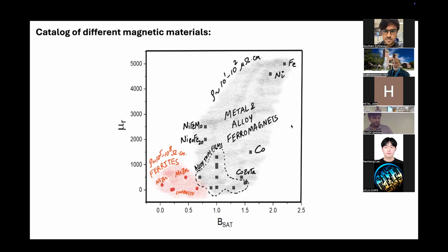Yeah, if you didn't have any magnetic material, then your permeability is going to be 1. And you can apply any amount of magnetic field and obviously it won't saturate and it can go to any frequency, right? But the only caveat is that because your permeability is 1, in order to get a certain value of inductance, you need a large area or a large size of your inductor, right? So it's really a compromise between your losses, frequency, and inductance. And I'll talk later, you have many things that oppose each other, okay? One of the things that opposes is the frequency operation in mu r, which I talked about, right?